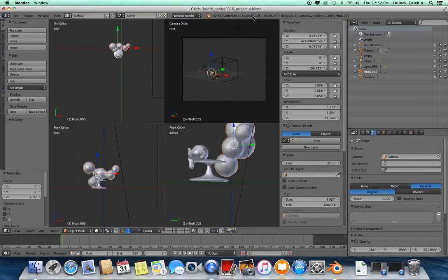Now it also says that it has 10,000 faces present in the scene, which tells me that there are certain polygons in the scene that are made of square or oblong forms that are non-triangular. So when we export, those forms will actually get split or broken down into triangles. So this number could effectively double, and we could end up adding to our triangle count a lot more. But we're well under the number. For 19,000, that's nothing. So easy fix.